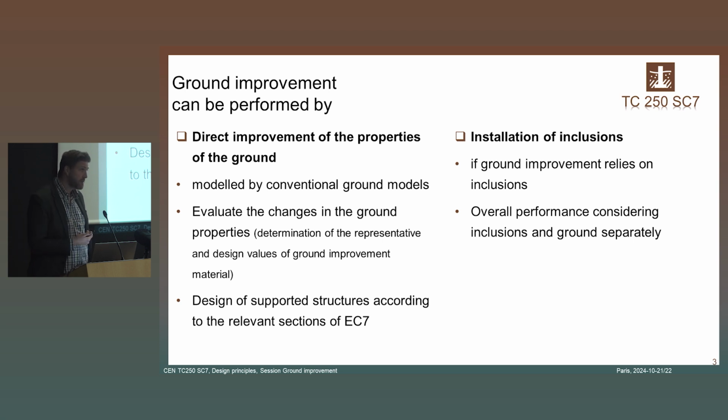We have another possibility, it's to install rigid or non-rigid inclusions into the soft soil, and in this case we have to consider the overall performance, taking into account the resistance of these inclusions and the resistance of the soft soil.